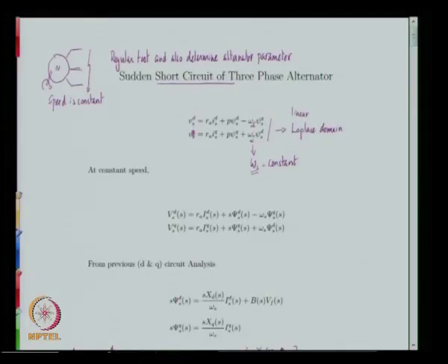We started out with our familiar equations in the D and Q axis for the machine, the stator alone. We had used this formulation, which effectively eliminates the rotor variables. Since you have the derivative of the stator flux linkage, which in turn involves the flow of current in the dampers and in the field winding, we then saw the equivalent circuit along the D and Q axis.